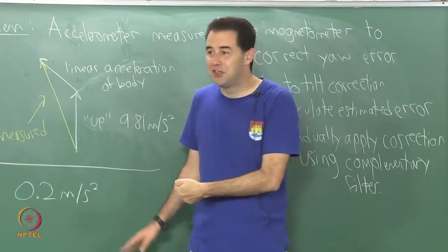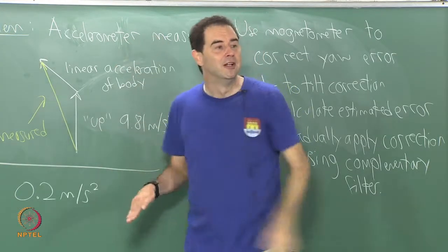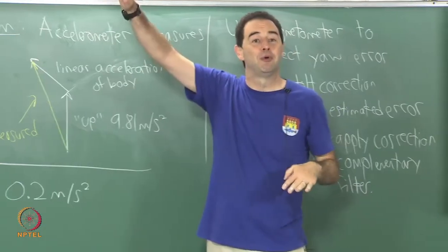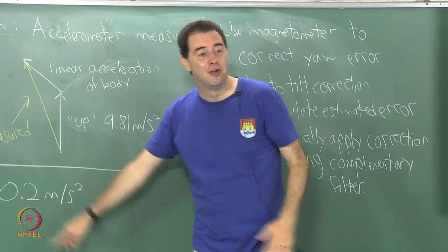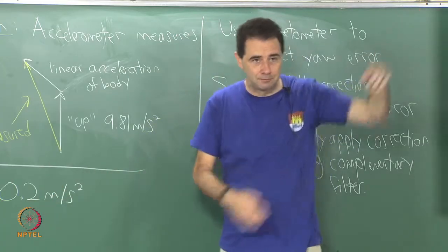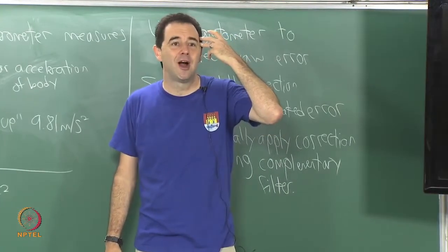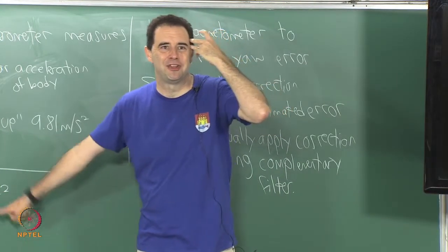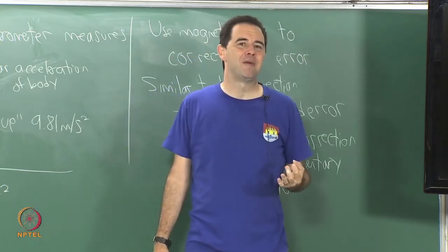But if you integrate twice to get up to position, you're two integrals away from the position. Then it ends up with a fast quadratic growth rate. A simple offset like this, a simple fixed error, will cause a quadratic growth rate. So it's very much as if your head has a fictitious rocket thruster attached to it that's thrusting at this rate, and it makes you shoot away. And so that's what gets very, very bad about this.